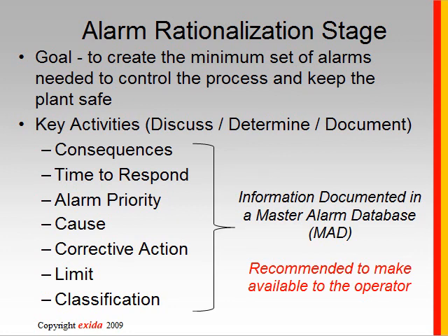Then we're going to look at the time to respond. How much time does the operator have to respond to that alarm? Based on those two criteria, we're going to set the alarm priority. Then we're also going to discuss and document what's the cause, what's the corrective action, and then we're also going to determine the appropriate alarm limit and classify the alarm.